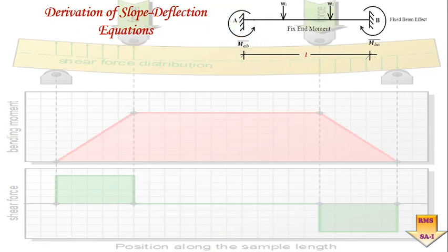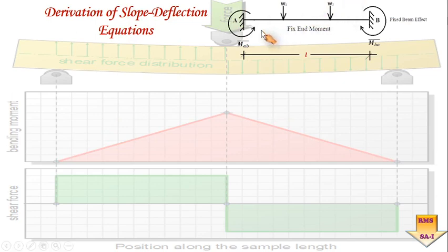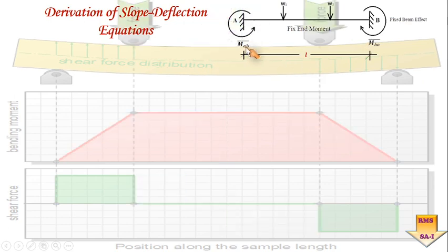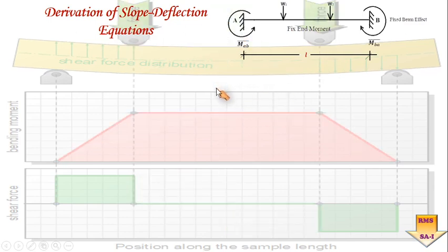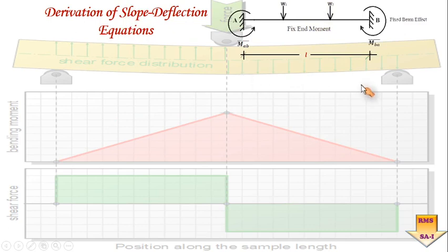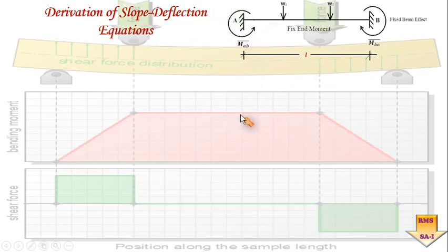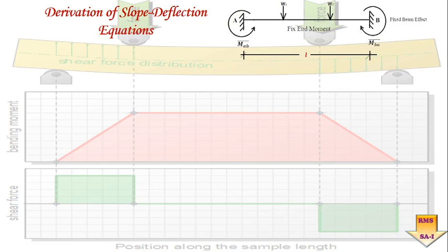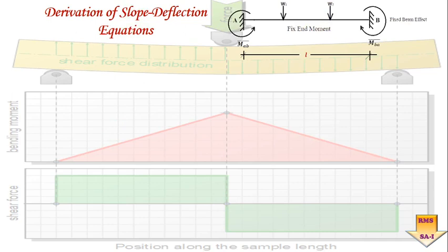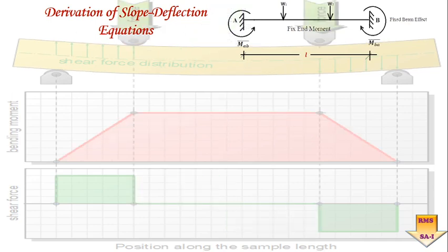But as we are dealing with the displacement method, due to this applied load there will be displacement at A and B, which will introduce moments about A and B. After compiling the fixed end moments and the moments induced due to the displacements at each joint, we get a set of equations, and after solving those equations we will be able to find the final solution. So this is the first case: one fixed beam AB with loadings and the fixed end moments. Now let us understand what exactly is to be done.